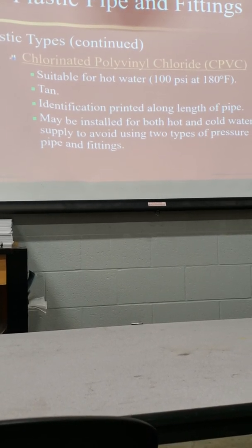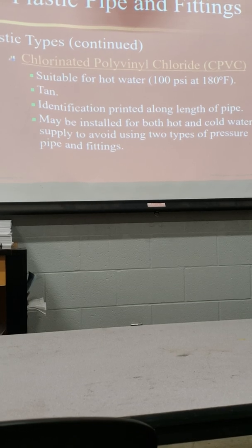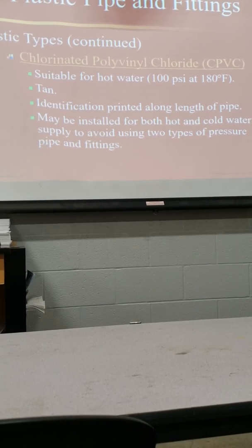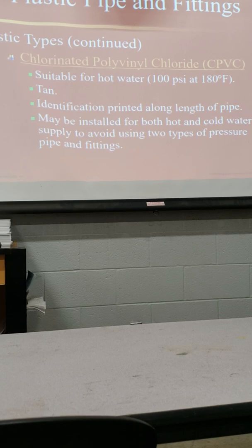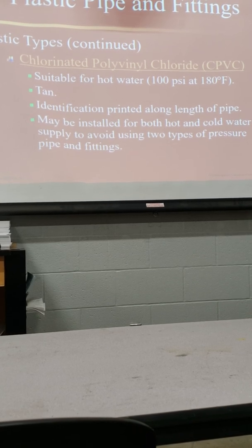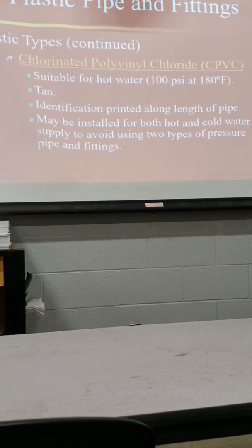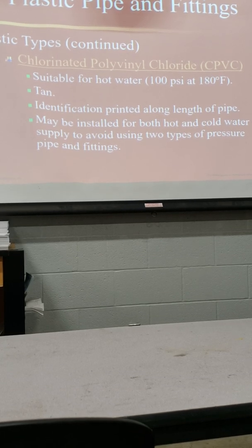Typically, they want 24 hours on most glues. They do go together similar to PVC in what's called a solvent welded joint. So we're actually welding the pipes together using chemicals.